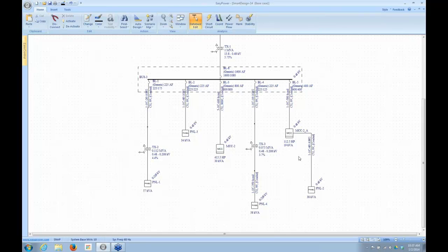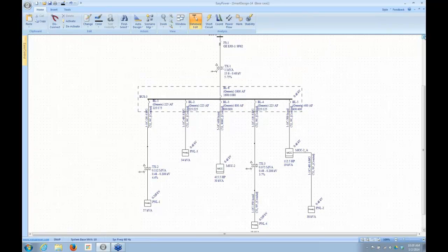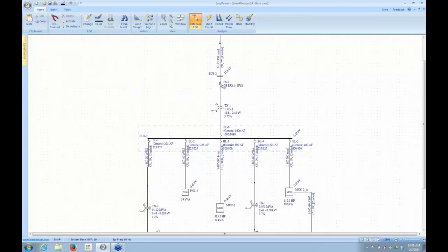Okay, so that's kind of the basics. Remember, we're limited to low voltage equipment. It's not going to size this fuse for me. It will size a medium to low voltage transformer based on what's in those design sheets, right? So it's going to pick the one that's large enough to do the job.